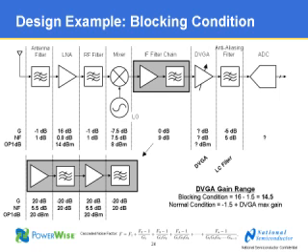You can see that each filter is generally a SAW filter with a pretty high loss, about 20 dB loss in this case. You need to have some buffer amplifiers or IF amplifiers to overcome that loss. So the cascaded numbers for this 2-stage filtering are about no loss through the filter, but about 9 dB of noise figure. It's being followed up by the DVGA. I put a question mark for now because we want to calculate that and back calculate it.